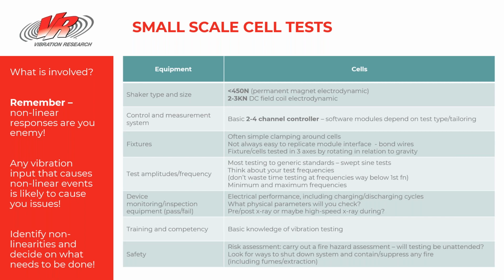There are packaged cell level vibration tests for UN 38.3 to get transport clearance for shipping cells, but that doesn't really require a lot of fixturing. Generally you rotate these fixtures around, and you don't really need to do cell vibration in relation to gravity, so you can rotate the product.